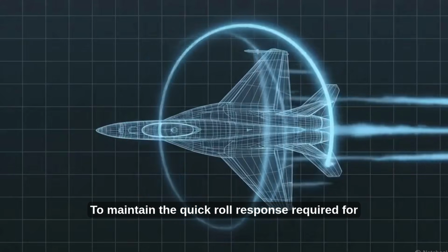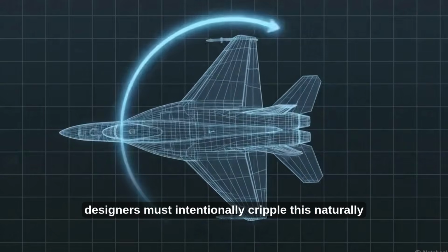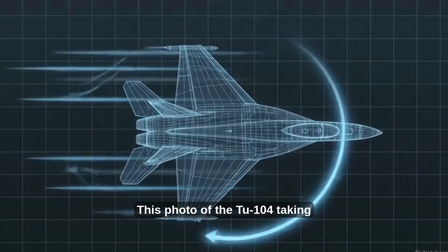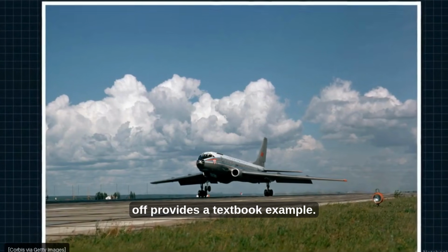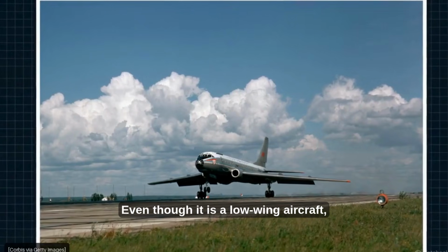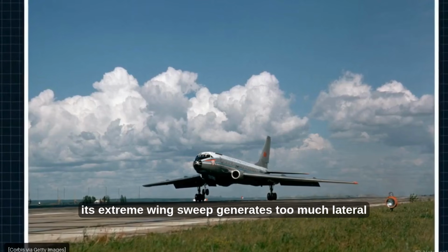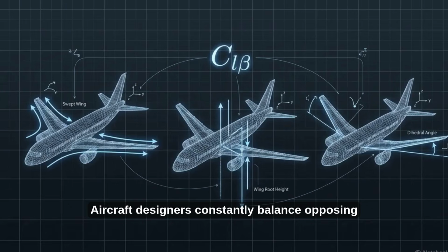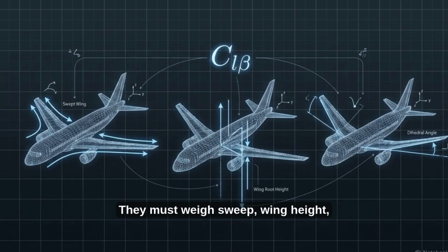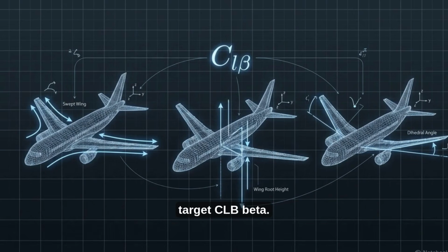To maintain the quick roll response required for combat or high-speed maneuvers, designers must intentionally cripple this naturally occurring stability. This photo of the Tu-104 taking off provides a textbook example. Even though it is a low-wing aircraft, it requires an anhedral droop purely because its extreme wing sweep generates too much lateral stiffness. Aircraft designers constantly balance opposing aerodynamic forces. They must weigh sweep, wing height, and dihedral against each other to achieve a specific target Cl beta.